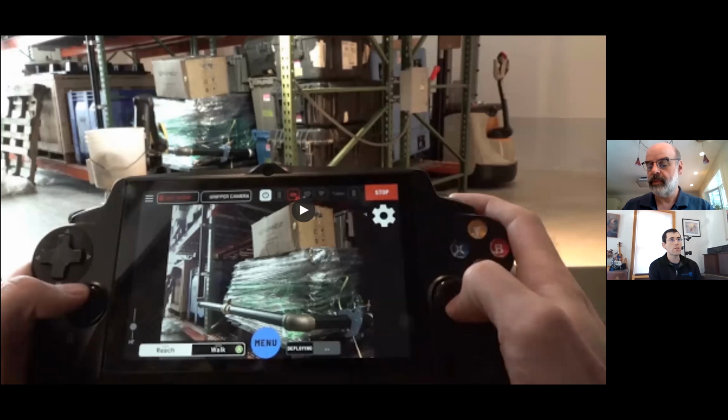So we've got a great question about integrating SPOT with AR and VR using 3D motion controllers. When connecting through the API, the question is, are we able to send target coordinates and rotations to the gripper, or would manual control require direct joint manipulation? Yes, absolutely. Control of the arm is either through direct joint commands or through what we refer to internally as drive the hand mode, which is just specifying a location and orientation for where you want the gripper. And we support doing that.